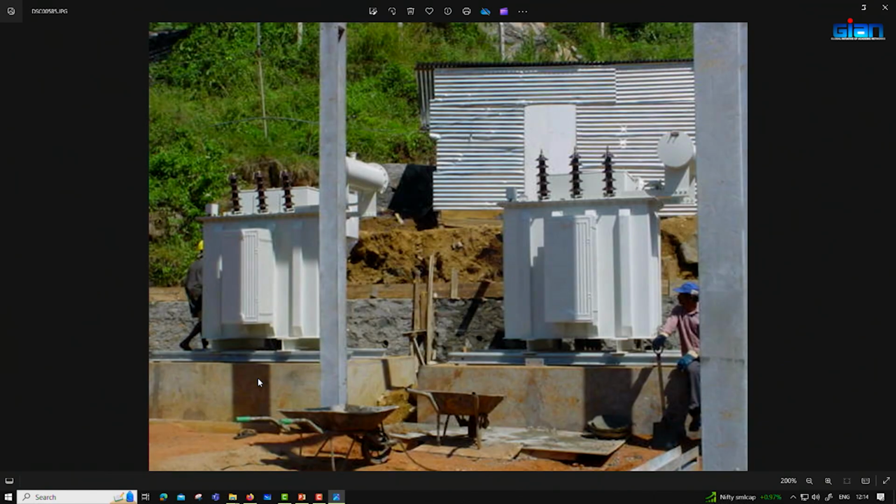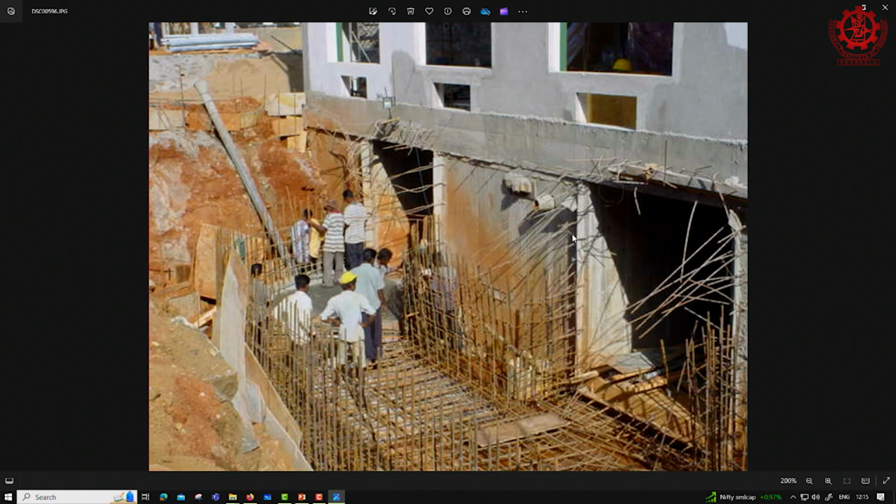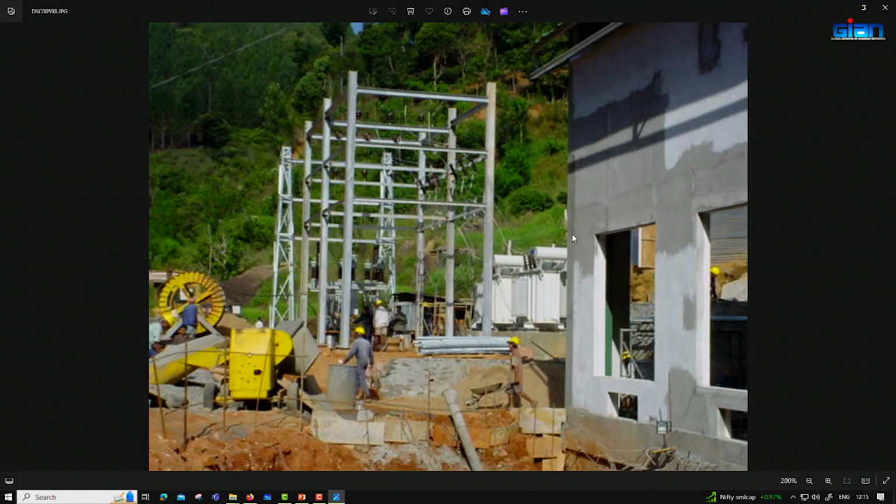This is the outdoor switch yard where we want to step up to 33 kV, right. In this plant one machine is 1.25 megawatt, and we decided to generate at low voltage, 415 volts. So, it is a 415 volt to 33 kV step up, and that is where we sell electricity. Here the tail race is being further constructed. This is the switch yard, right, switching equipment, lightning arresters and the main breakers etc. installed.